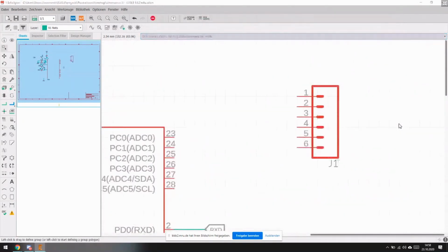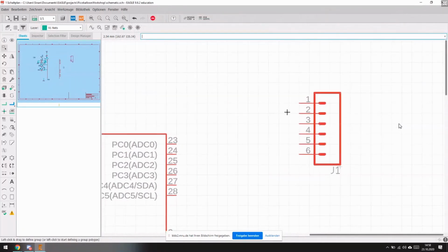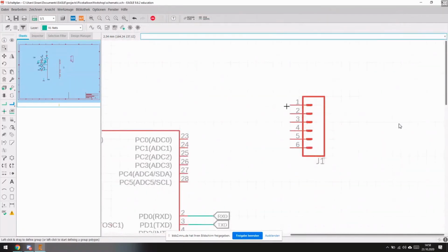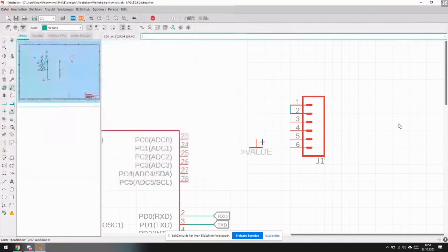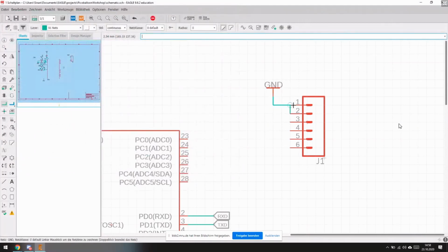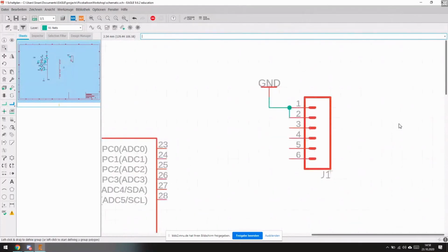So now we can connect our pins to the header. There's kind of a basic layout system that programmers use, or serial to UART programmers, so to speak. So we will connect 1 and 2. Connect this to G and D. If I'm going too fast, just type it in the chat, please. Connect the G and D, or ground, to our header.